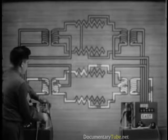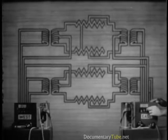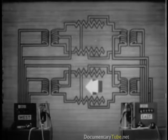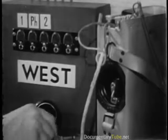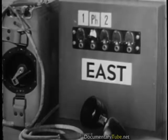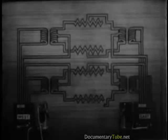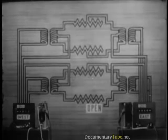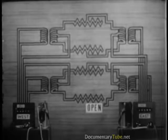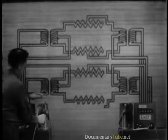The faulty circuit is no good until the short is cleared. It follows that if both side circuits are shorted, both are useless. But the phantom is still okay. Now let's assume that our trouble is an open in one of the side circuits. This is the extreme condition of unbalance.